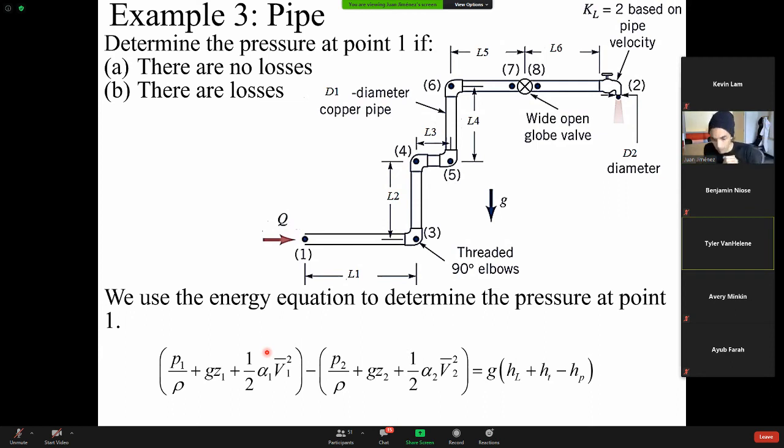And so how do you know if your guess is wrong? Based on the Reynolds number. So what's a critical Reynolds number for pipe flow, for internal flow? So are these the numbers based on if it's laminar or turbulent? Right. Okay, I don't know it off the top of my head, but before today, at 4,000 and above, turbulent; 2,100 and below, laminar. Okay, just know that number, and it's a good number to know as an engineer. It's good to know that if you're somewhere at 2,000 something, 3,000, you're going to be transitioning to turbulent flow.